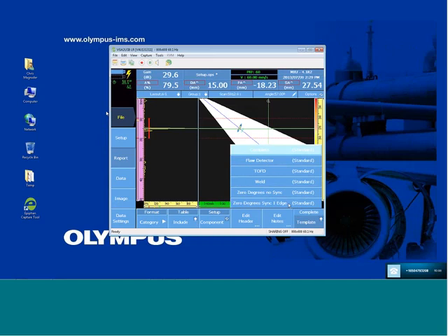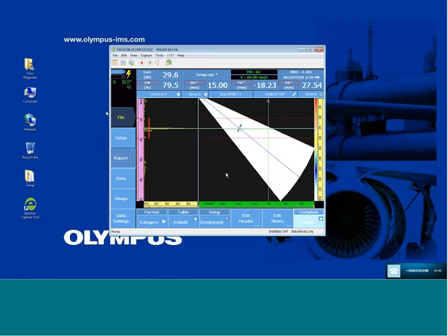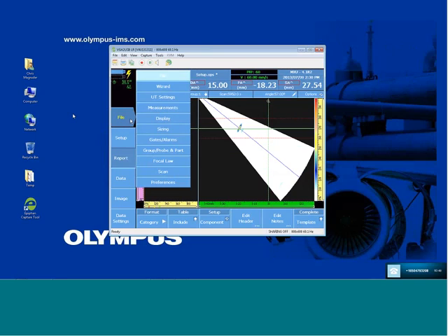So what happens is, when I'm in a wedge delay calibration like I am now, the software is remembering the time of flight on either a radius or a side drilled hole. Based on the number of points and optimization of the range, the accuracy of that reading can be manipulated by the operator. But if the probe is in tolerance, like it is now, I haven't performed a previous wedge delay, I just have the ability to accept it prior to actually calibrating it.